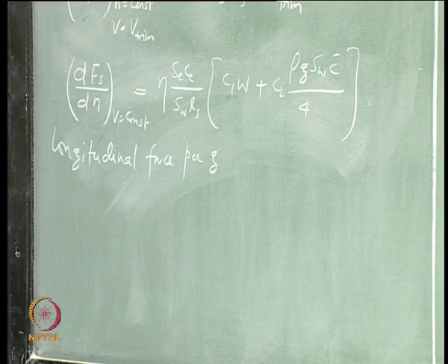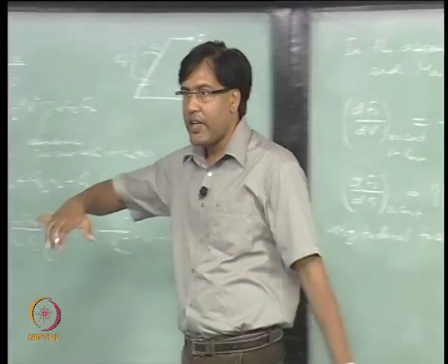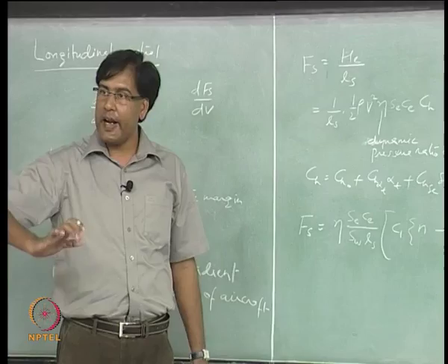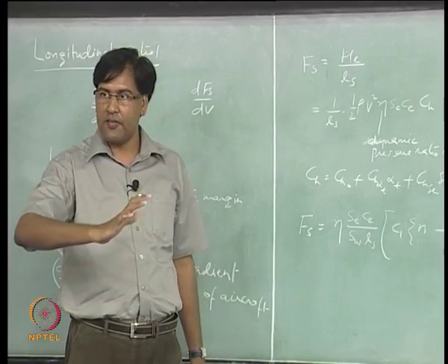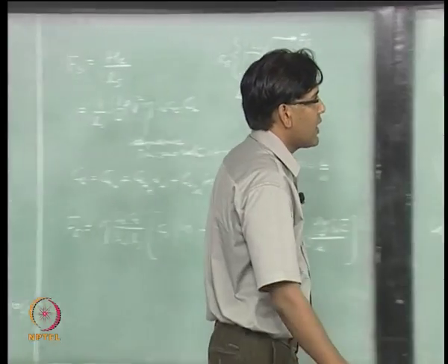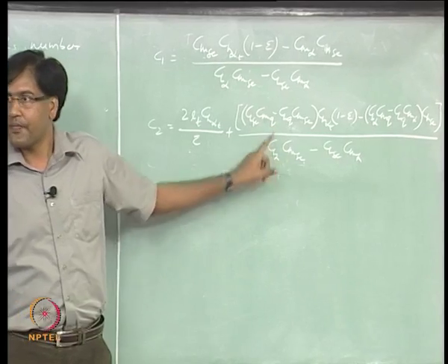You would notice this Q appearing here, right. Q is the pitch rate, okay. When you are trying to do a pull up maneuver, right, there a rate is involved. You want to pitch up the aircraft, right, when you want to do a pull maneuver. So that is where these derivatives are coming into picture.